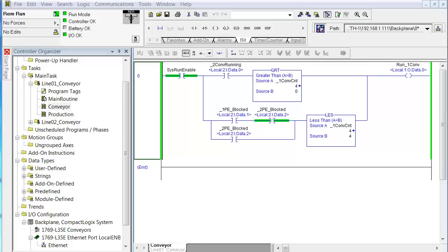That is, typically panels should be laid out with a minimum 20% spare space, meaning that any area of the panel, any component designation, any category should be able to expand another 20%. In this case, the L45, its power supply, the SERCOS card, and the Ethernet card would just fit into that 20% category. So this is a very doable scenario out in the field.